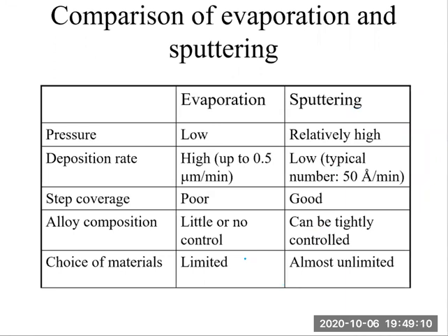Now let's have a brief comparison of evaporation and sputtering, or sputter deposition. First, the deposition pressure. Evaporation needs very low deposition pressure, typically less than 10 to the power of -6 torr. Why do we need such a low deposition pressure?